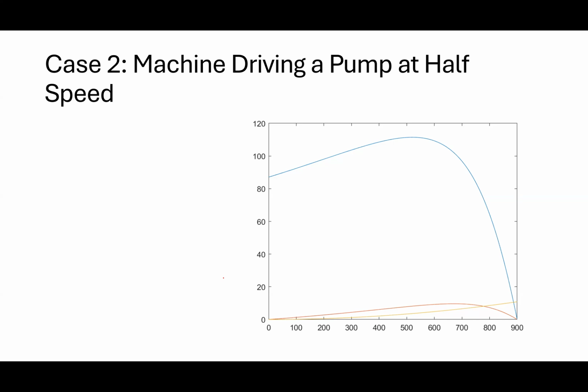Now, what sets the synchronous speed? Well, it's how fast the field from the stator goes around. So what did I change? To make this happen, I changed the frequency of the electrical side, 30 hertz. So I'm no longer applying a 60 hertz current to this thing. I'm applying a 30 hertz current to it. What I'm doing is I've taken the frequency down to 30 hertz and I've made the voltage 1/2 of whatever it was. So the line-to-line voltage became 1/2 of 208. I'm applying less voltage, less frequency.